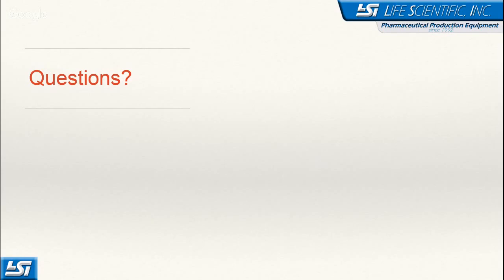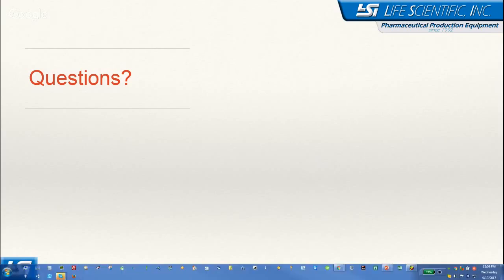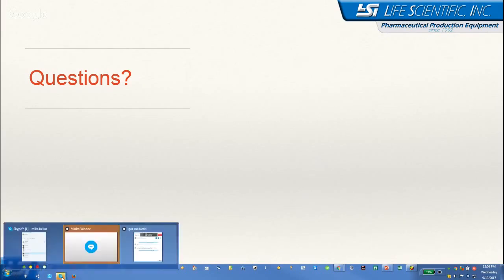You'll have dimple jacket. Now, with dimple jacket, you have a little bit of a trade-off with pressure drop because there's a high drop through the jacket. So then you have to size your pump that pushes the media through the tank wall, but you do get a very efficient turbulent flow. So your U values then can be a little bit higher. Now I know in the example I gave a very conservative U value, but you can use a little bit more aggressive U value when you're using the dimple jacket for the turbulent flow.